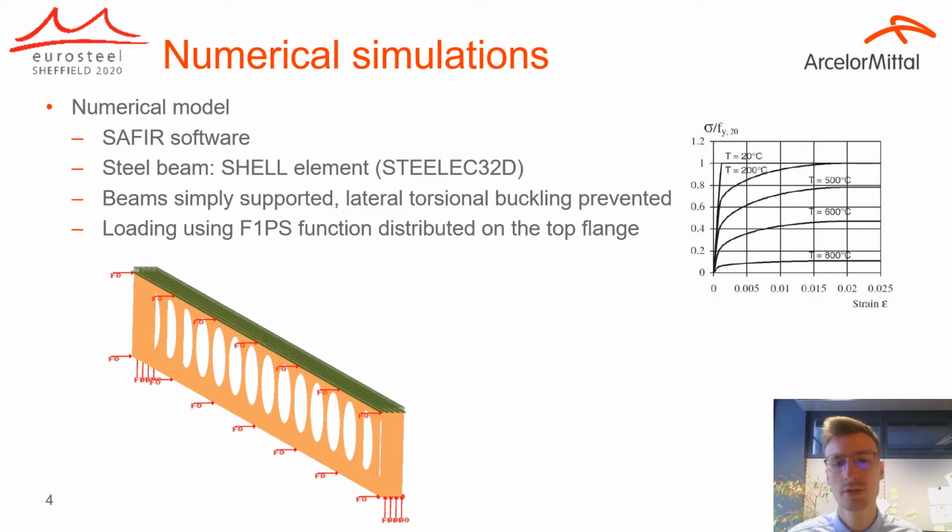So here it's a distributed load on the top flange, but we also tried other loads such as point loads. And the last point is the deformed shape we imposed on the web. It is equal to 0.0025 times the height of the web for the sine curve amplitude.